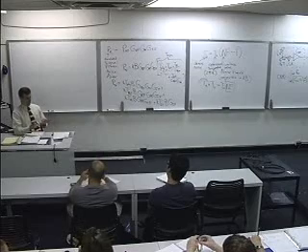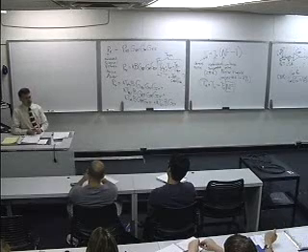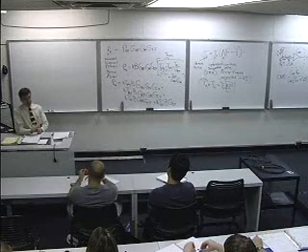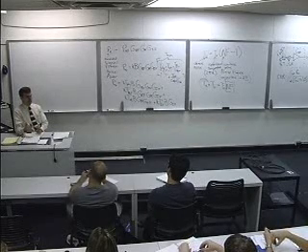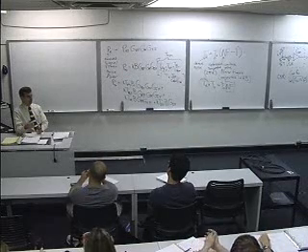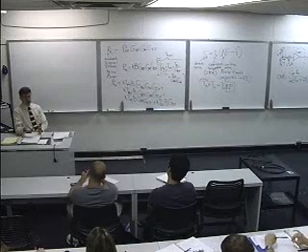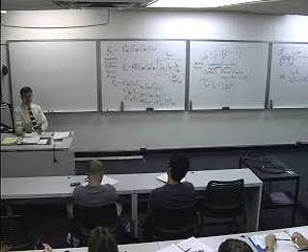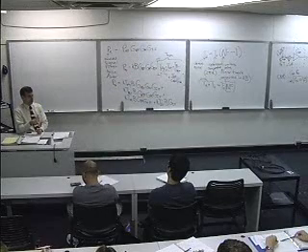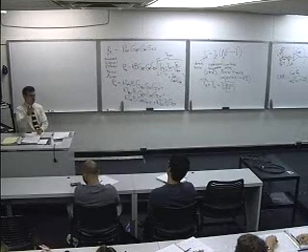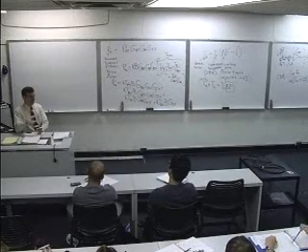Now, there's this other effect where, if you have a system and you've got baseband circuitry, intermediate frequency band circuitry, RF electronics on it, and all these other components, and they're connected to each other, whether they want to be or not, through signal lines and also power supply lines, because all of these require devices that draw off of power supply. Then there are actually these weird pathways, and sometimes it's just pure radiation. A signal trace will radiate a little bit of its energy, and it'll jump to another board in your box and fold into your signal that way. Or sometimes it'll go through a power line trace and enter in.